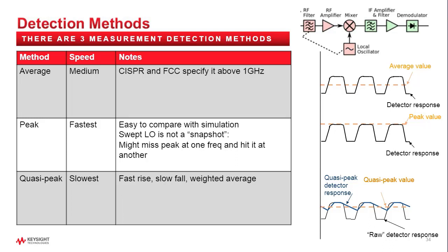So there are a couple different methods: average, peak, quasi-peak. If you look on the right, there's a little graphical description of the average value of a pulse signal, peak value, and then what's described as a quasi-peak. And in the simulation environment, we need to be able to replicate this as well. Now, one of the things we don't do in the simulation environment is the quasi-peak, because the quasi-peak is used for aperiodic signals that take place over 4 or 5 seconds, 2 or 3 seconds.